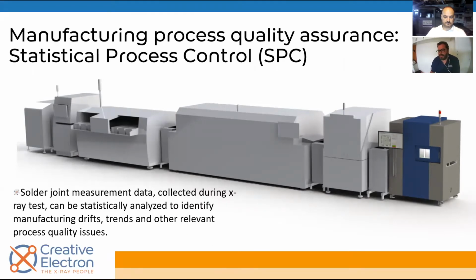One of the main things we also want to introduce is that when you have an AXI, usually it's at the last step of your process. An AXI can collect data from other machines and give you an overall picture of how your line is doing, depending on what sort of defects. Certain defects are happening at certain different processes, so you can go back and fix that process to have a more efficient overall result.